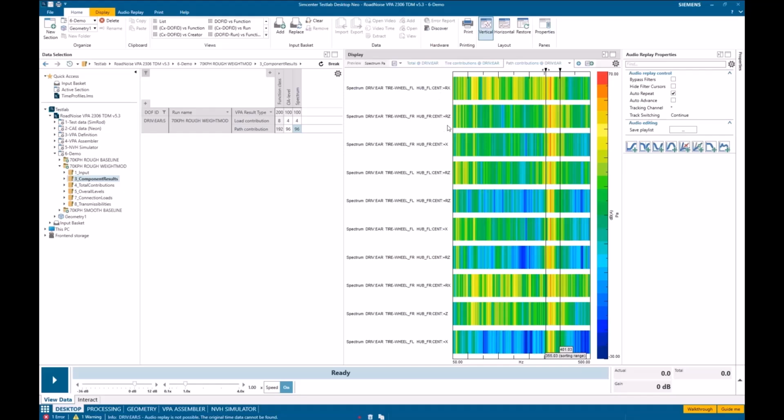Second is the rotational around the Z. Okay, so the RY is the rolling axis, and we don't bother with this because that's sort of a free rotation. And so this is rotation around the other 2 directions, both toe and camber. Essentially those 2 rotations, and then the X direction, and then rotation in the Z, et cetera, et cetera.